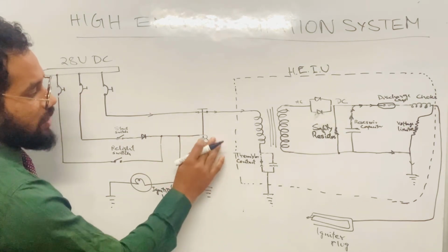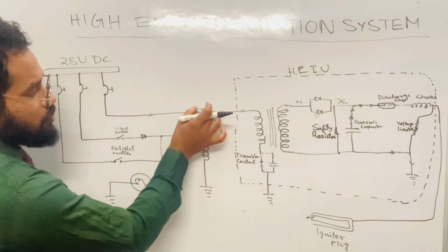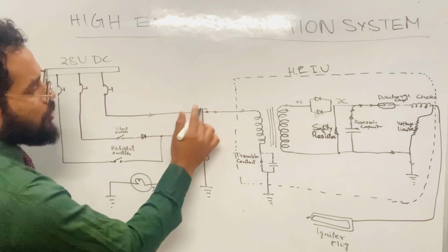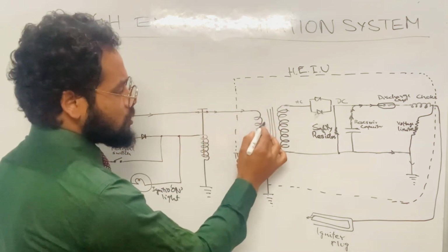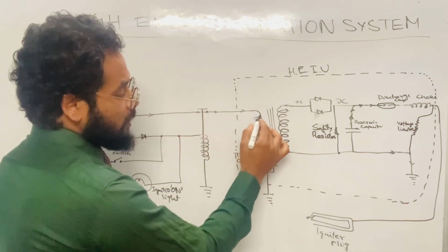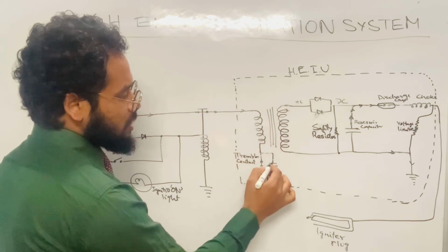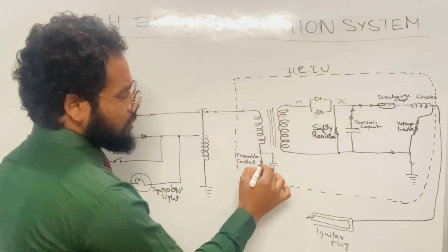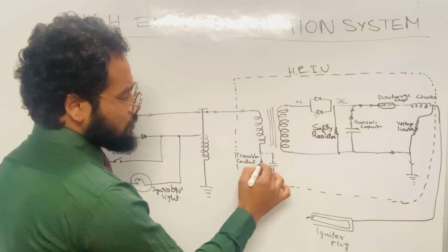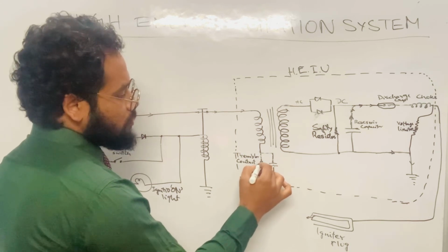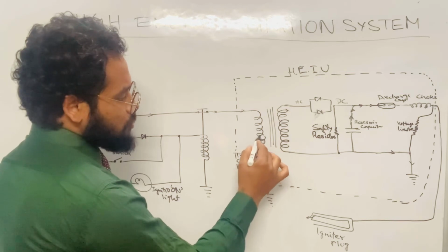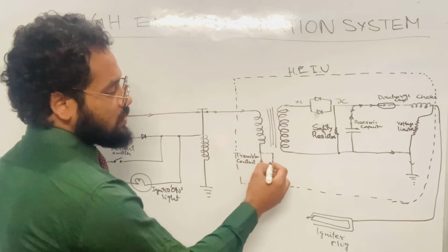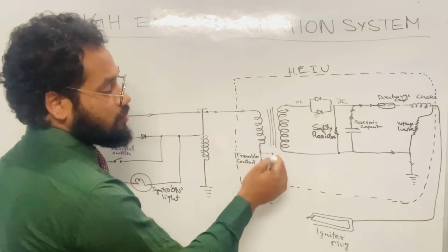So this will magnetize the coil, and when it gets magnetized, it will pull this contact down and close this contact. So the current which was waiting at this point will go ahead and pass through this coil called the induction coil. When the current is passing through this induction coil, it charges this capacitor, and when this capacitor discharges, it will cause these contacts to close by means of an arc. So when this closes, the current flowing through this coil gets the grounding path and it gets magnetized, and soon after, as the capacitor has discharged, it needs to be recharged again.